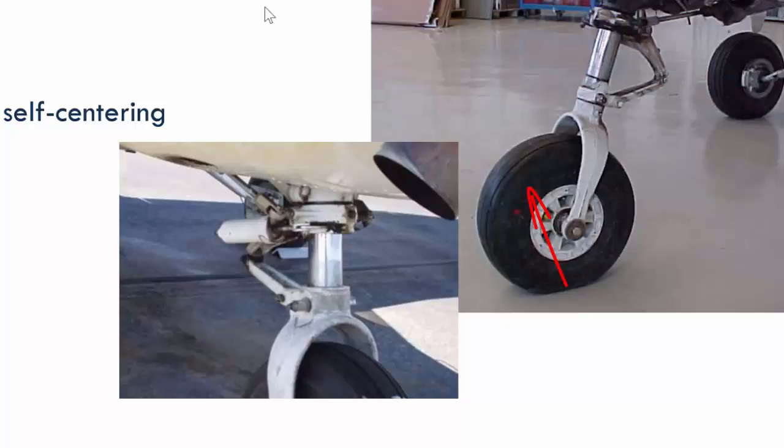This torque link connects the upper part of the cylinder of the strut and the lower part of the piston together without creating resistance in the movement of the piston up and down. So it links together the upper and lower parts of the strut and allows keeping the direction of the wheel together with the cylinder.